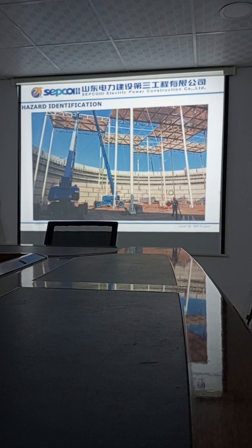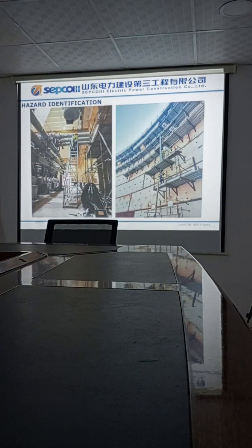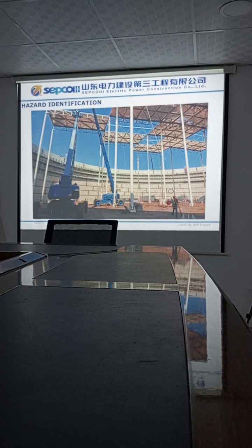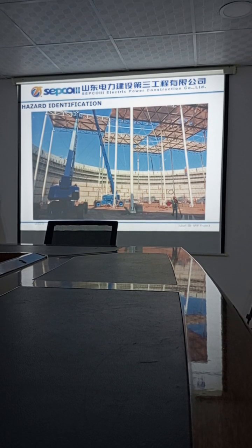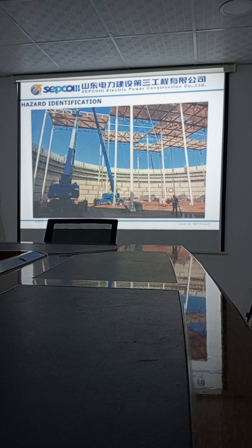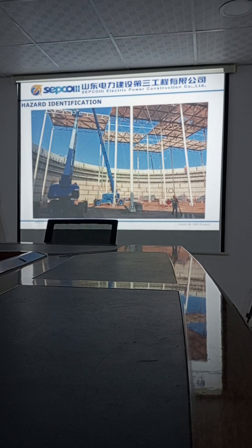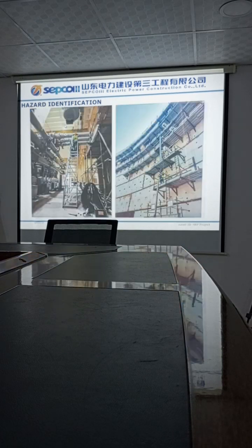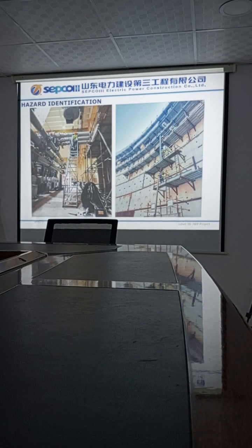What is the hazard here? You can see it is high, working at heights. So it should be barricaded. This support should be secured because it can be tangled and can collapse. Pulling hazard, fall from height. So this is mostly here, alone.